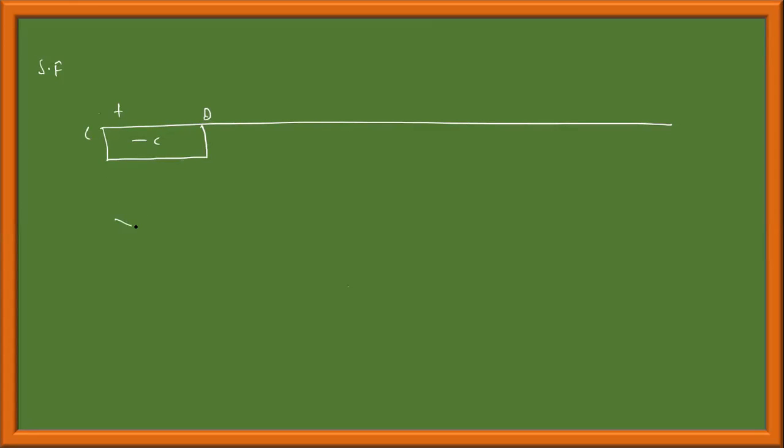Next, shear force, if it is negative like this, I'll take all the four cases. This is positive. The shear force is negative constant. The slope positive in the sense it is moving upward. Moving downwards, this is point C, point D. Moving downwards like this is negative slope. That you should know. Check what is positive slope. Any curve which is moving upwards is said to be positive. In the other sense, when it is moving downwards, it is negative.